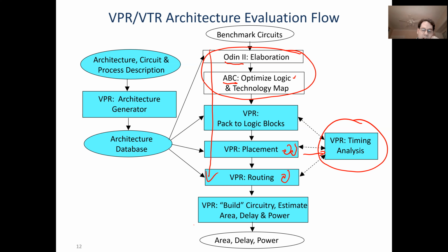Okay, so at the end of that, you get out a report on, for this particular FPGA that you were thinking of, how well did each one of these benchmark circuits map to it? How much area did you need? How fast did it run, and so on.